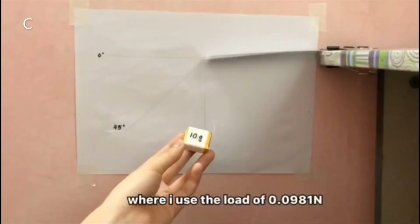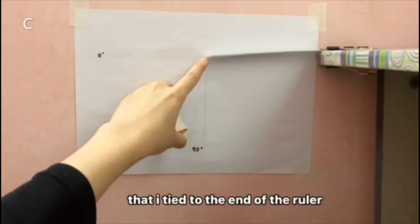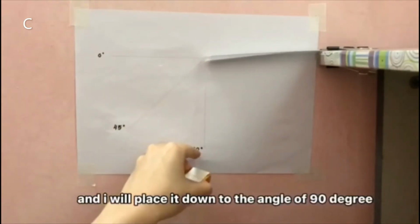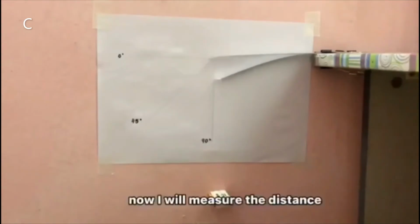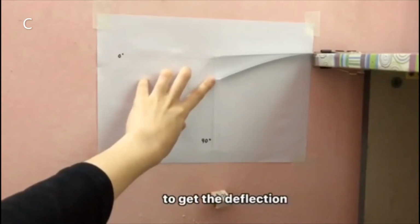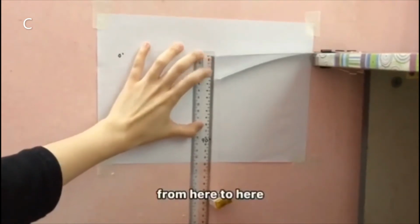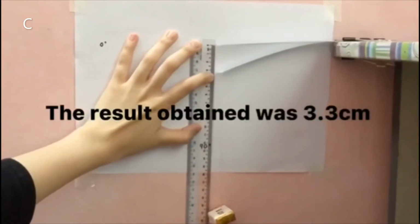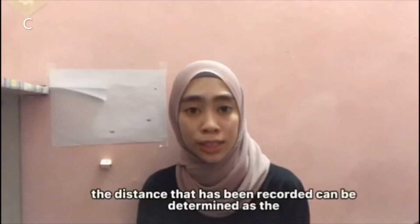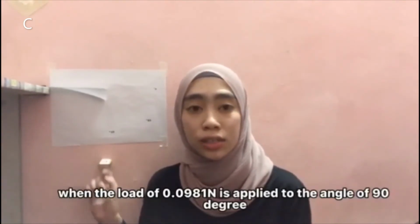I use the load of 0.0981 Newton or 10 gram of load that I tied to the end of the ruler, and I will place it down at the angle of 90 degree. Now, I will measure the distance from the initial placement of the ruler to the deflected ruler to get the deflection. Like this, from here to here. As a result, the distance that has been recorded determines the value of deflection when the load of 0.0981 Newton is applied at the 90 degree angle.